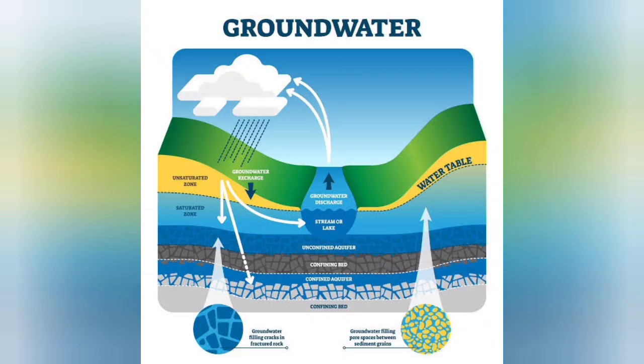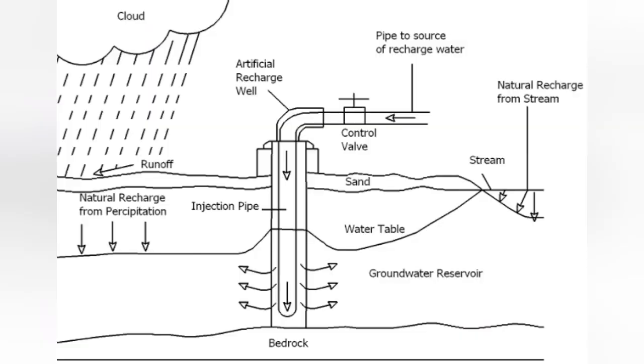Usually 4 types of source waters are available for artificial recharge. One is the in situ precipitation on the watershed. Second is the surface or canal supply from larger reservoirs located within the basin. Third is surface supplies through trans-basin water transfer. And finally, treated municipal and industrial wastewater.